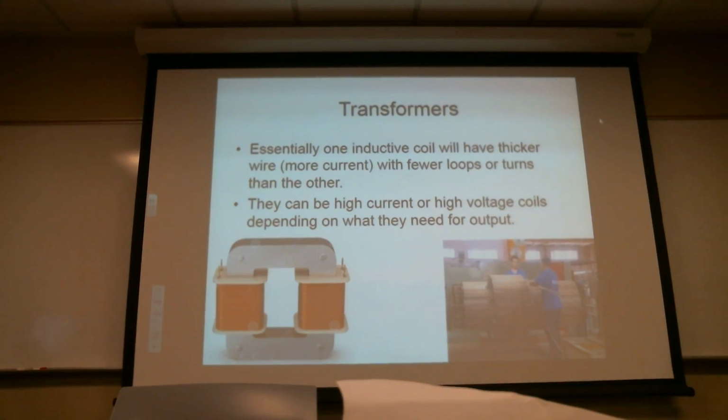So in the case of, let's use a magneto coil. If I look at the little generator in there spinning around 200 or 300 RPM, its top end is probably producing maybe 20, 22, 24 volts, something like that. And I want 20,000 volts out of it.